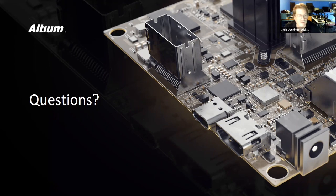So if you have heavier copper or different trace widths for your dummy components and the boards and you want to do vibration testing on them, there may be some additional advantage because of the heavier copper or the wider traces that wouldn't show up on your actual real design. So I would make the test board exactly the same as your normal production board, just to avoid any concerns or considerations, if that makes sense. Yeah, of course. That really makes sense.